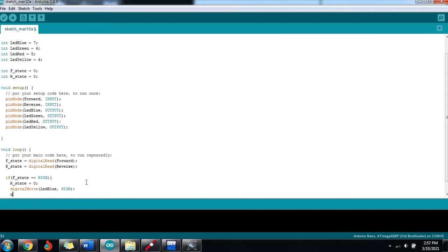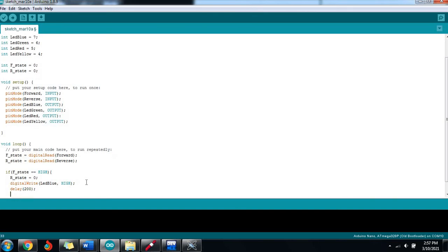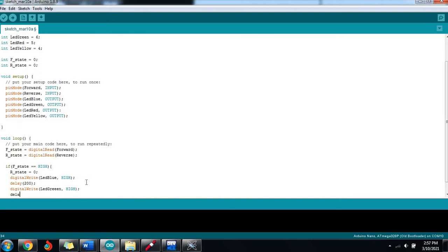Then we're going to have a delay of, say for example, 200, and then digitalWrite LED, what's next, green, then HIGH. So next, delay 200.